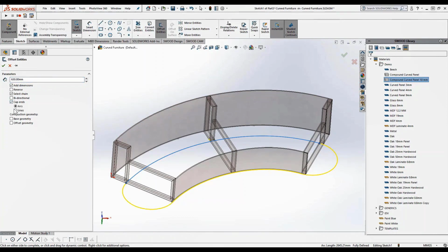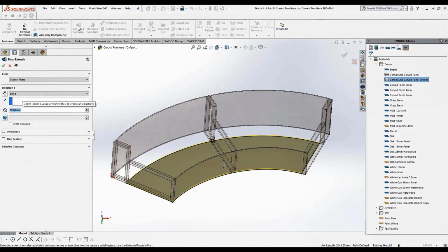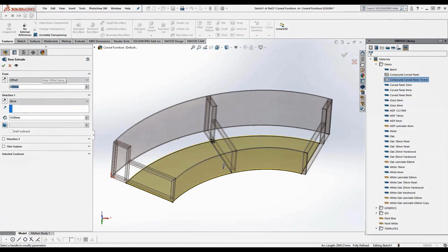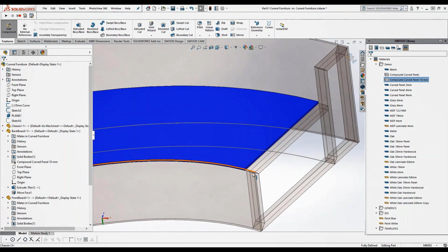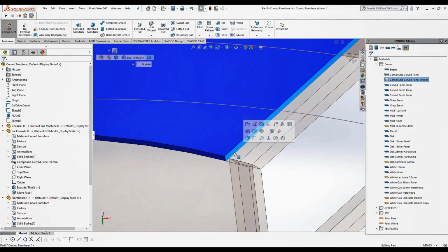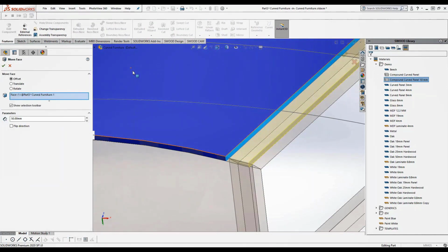So here you can see, I can just give it some extremity, and here my closed curve is created. Well, when I give it the extrusion, I can give it some offset distance, give it some additional thickness, and here the part is created. Of course, anytime when I want to modify it, I can extend this panel, give it some additional length. Okay, the work is done.